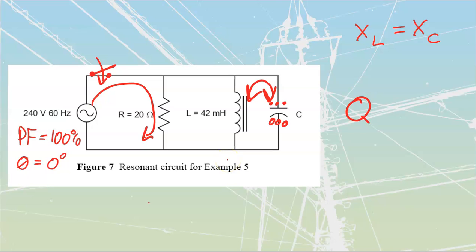All around, it's a fantastic thing, because we see that we can take a load that has some inductance, some properties like that, but we only once take that current in, and then after that, we just pass it back and forth. We just get to recycle that current, reuse it, and we're not continuously taking it from the source. Once again, we've got tons of these types of loads, right? Ballasts, transformers, motors are 3 big ones. And as a result, we've got a lot of these inductive VARs, so we're going to see a lot of using capacitors so that we don't have to continuously supply the inductive VARs.